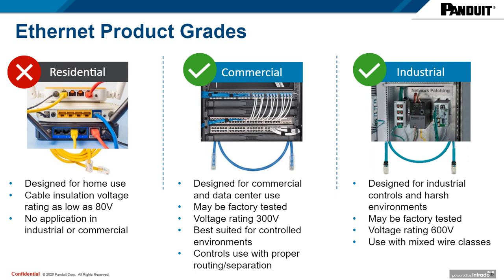And what that means is not only is there a wire map happening, but also the communications testing is done as well. So there's a Cat5e or Cat6a test done on that cable to verify it can be used in a system without having to test that cable in the field, which is a big advantage.